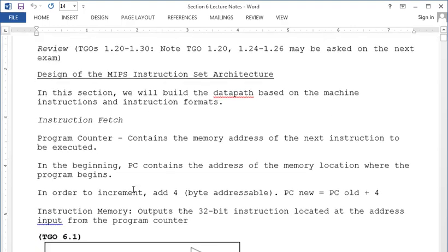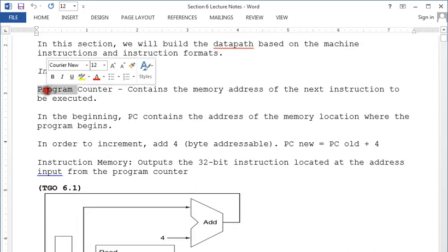So the instruction fetch stage is going to consist of a program counter, which, as you recall from memory addressing, contains the memory address. So in your section 4, you're going to be loading in those values from program.txt, as you recall. And you'll start at 0, and then you increment every 4. Now, why do we do the PC plus 4? Byte addressing, exactly right.